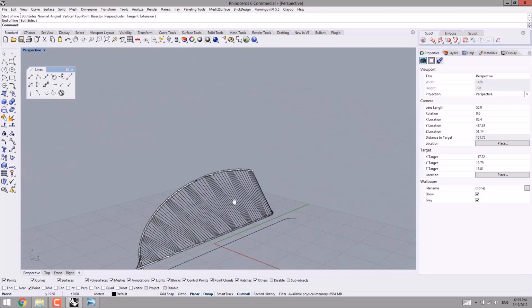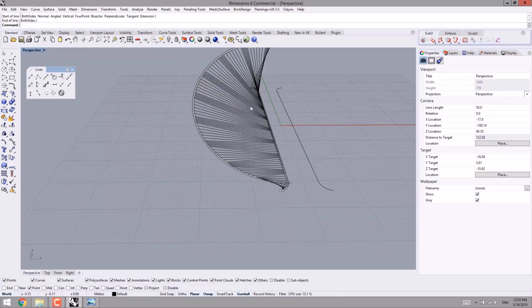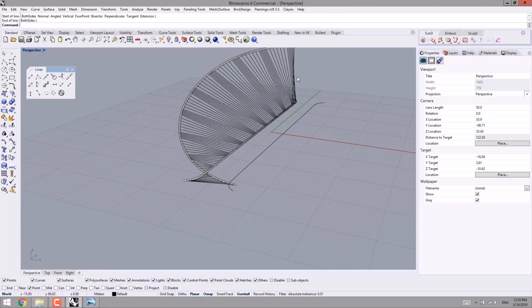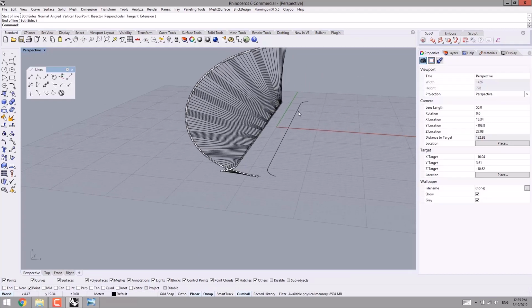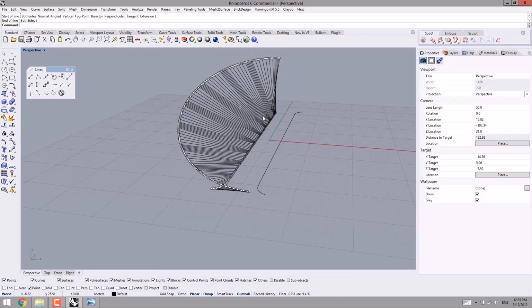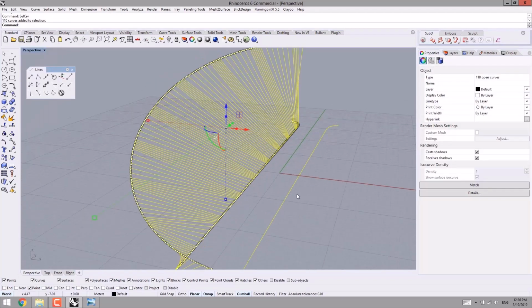Very well, and I sketch the last line this way. The next stage is to select the new lines that have just been sketched and then group them. By click and drag a window, I can select them, and then I can deselect the items I don't want selected, or I can search for SELCRV to select the curves this way.